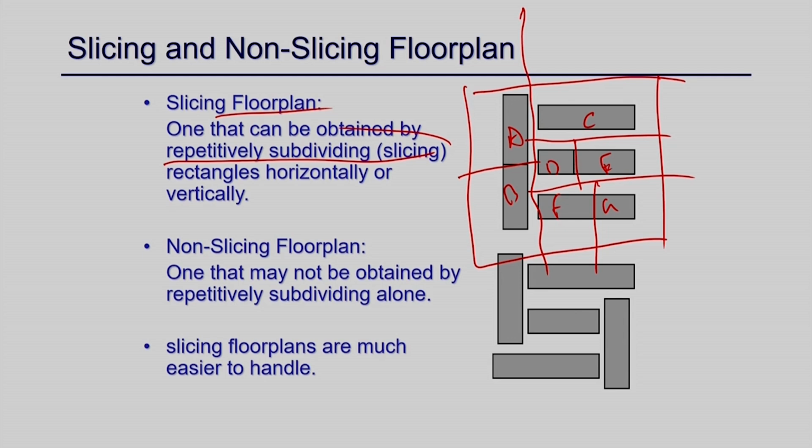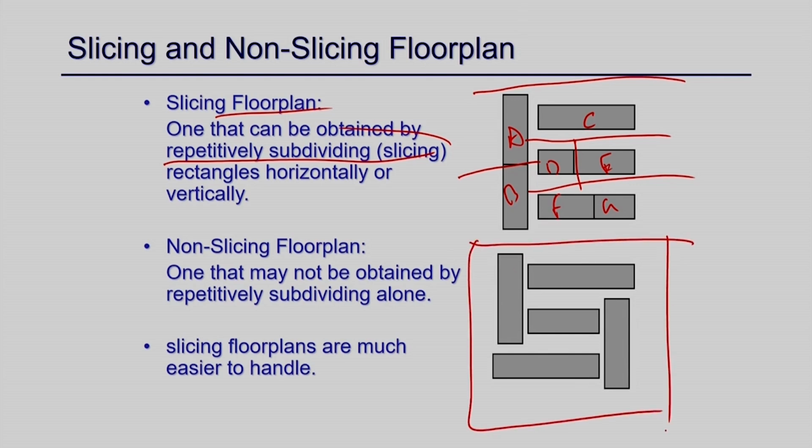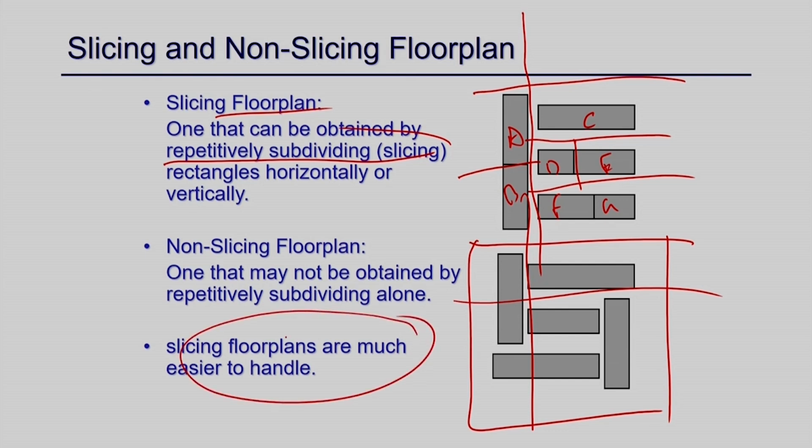On the other hand, if you look at this one, this is not a sliceable one, because you can see that I cannot make this kind of partition. If I try to make it, it will partition here. So, this is my component now, this is also not sliceable. So, I cannot make this kind of bipartition here, right. Here I just make a bipartition like this, but here I cannot make such a thing. So, this is non-sliceable.